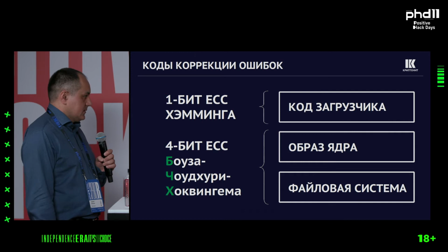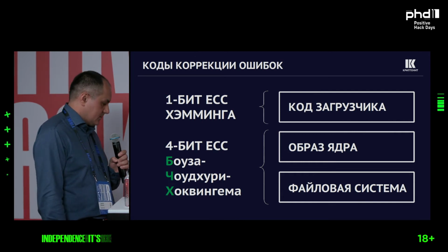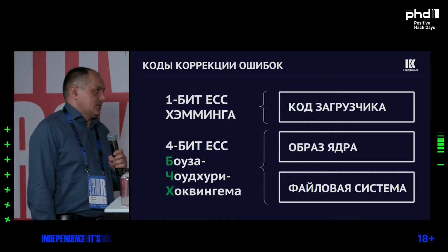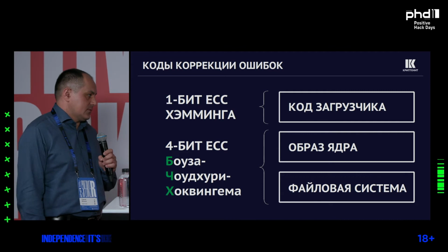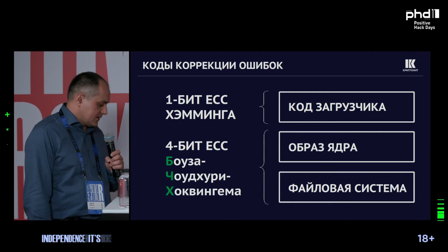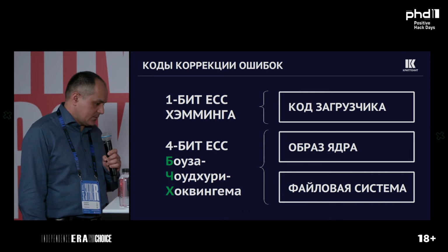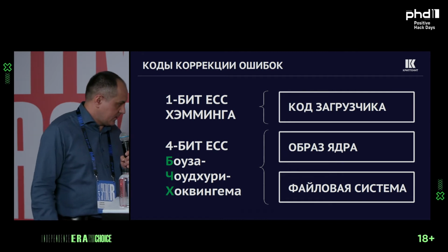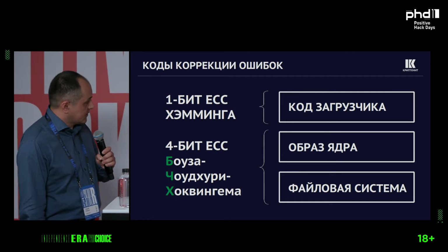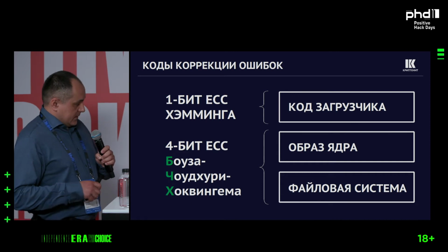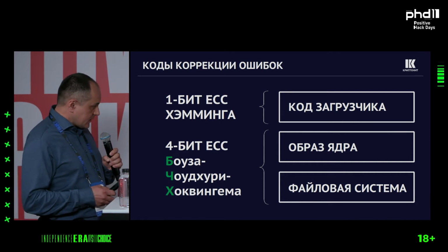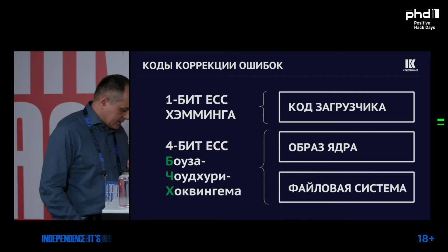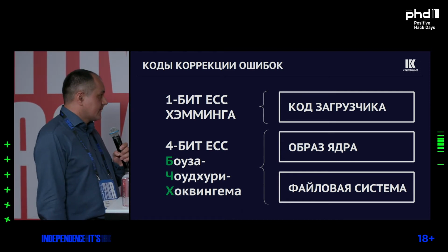After you read the memory dump from the device, you need to correct the bit mistakes. As memory technologies differ, there are different types, SLC, MLC, where the cell can store more than one state. QLC stores 4 bits in one cell. And this leads to an increased probability of bit mistakes.